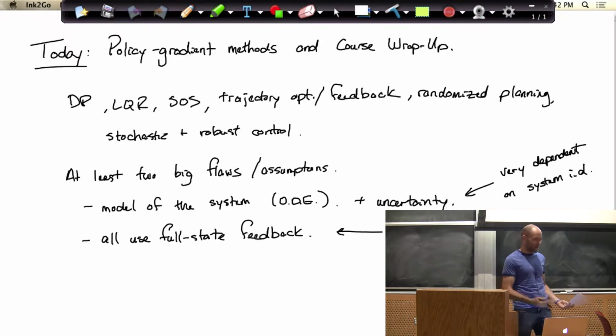In what way are they inferior? I can give you a better proof in some sense of the trajectory optimization plus feedback plus everything, but somehow if you have a pendulum sitting in front of you and you've just quickly estimated the parameters of the system, you don't know the friction exactly, you've got a quick and dirty state estimator that you put on the system and you just want the thing to swing up and balance at the top, you're going to have more luck immediately with an energy shaping pump-up controller than something that we've designed so far.